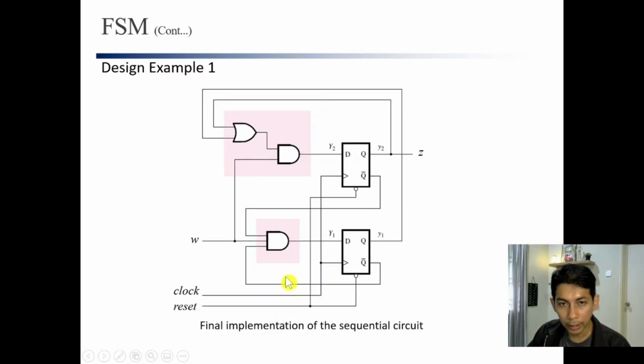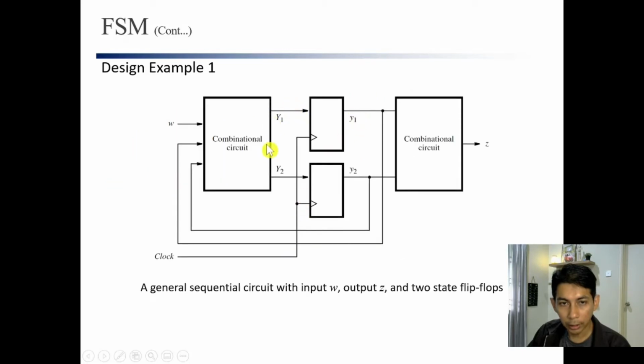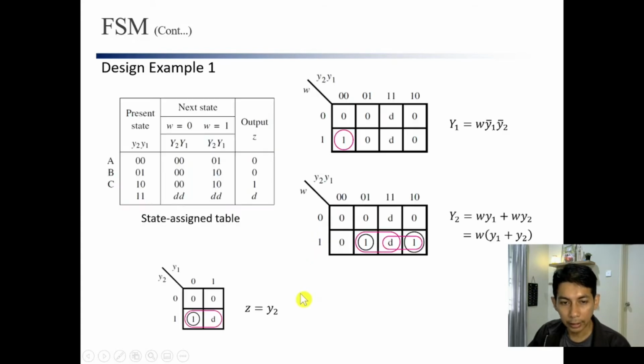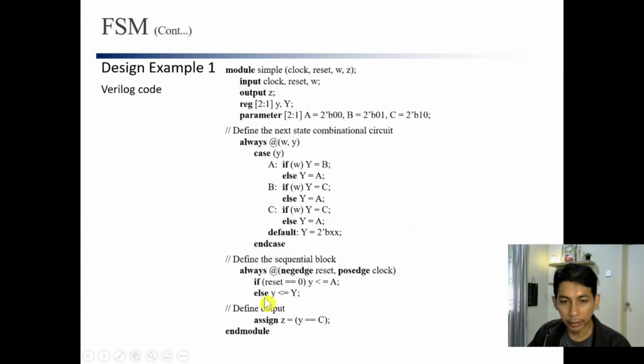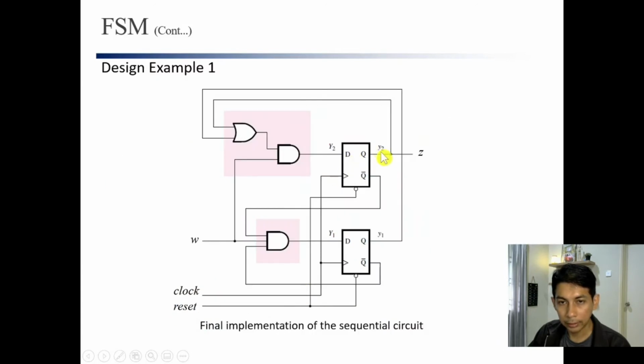Small y should be capital Y, right? So that we get the flip-flops. This code here will create two flip-flops for you, where the output of that flip-flop is small y and the input is the capital Y, just exactly like this, output and input.